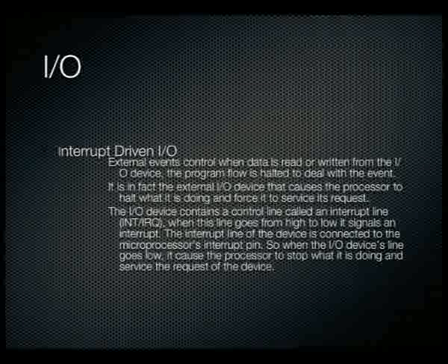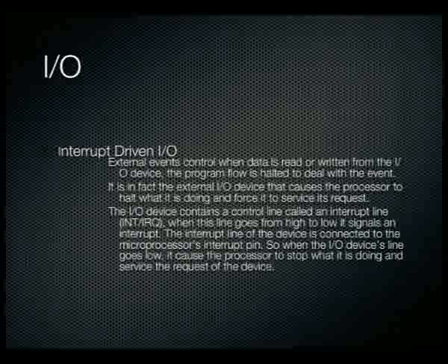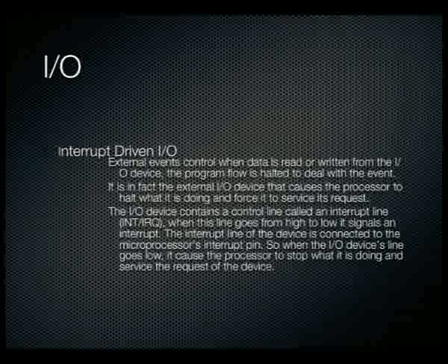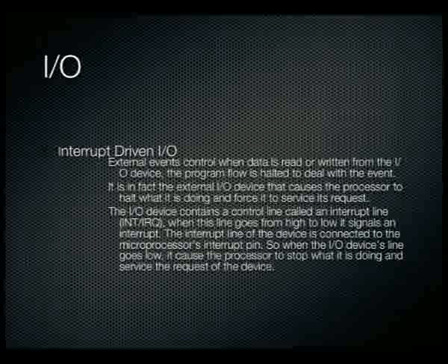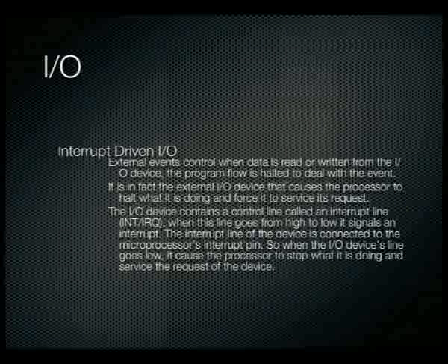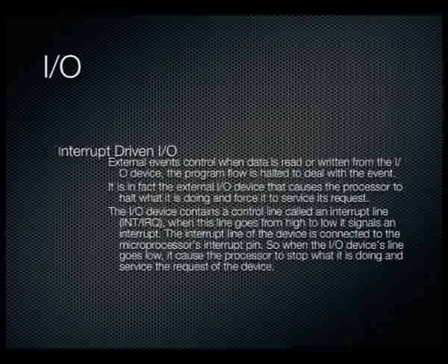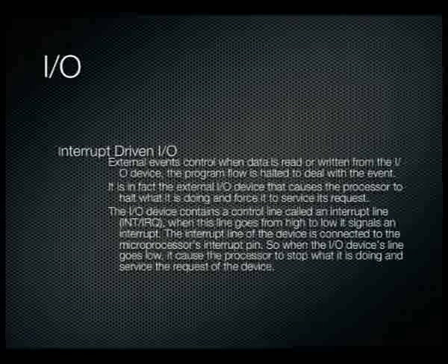So now we're not dictating when data moves around by the code telling it when to move. We're now moving data around when external devices tell us it needs to move. So some data has been received by the processor. The processor says, hey, I've got some data, deal with it for me. So now the processor is being dictated to by an I/O subsystem.